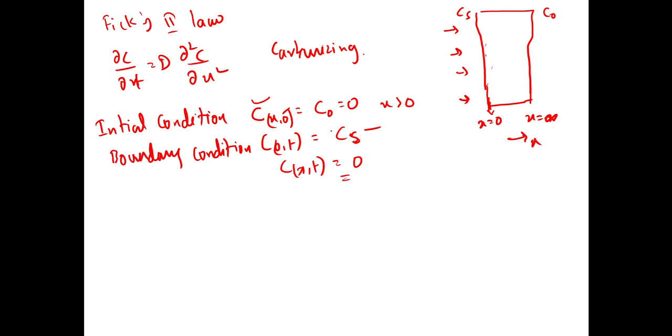And similar to the instantaneous planar source, how we have solved the second law of diffusion, similarly we have to take this second law and apply the Laplace transform, and then we get the solution for this carburizing diffusion equation.